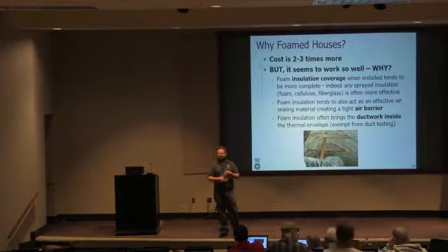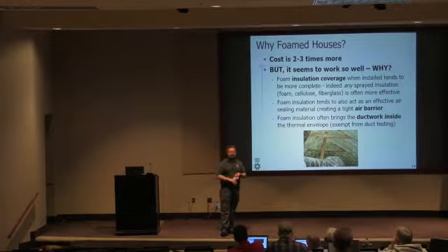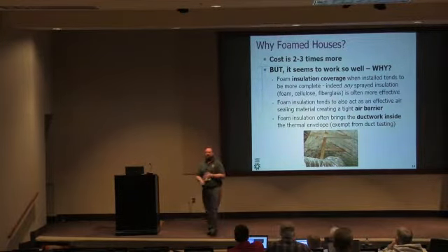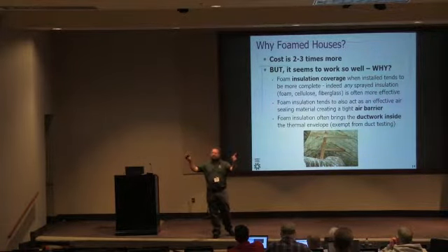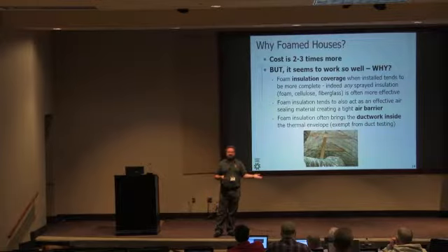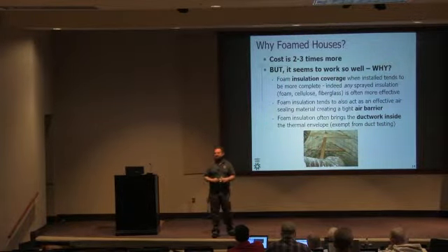Insulation is really crummy. Lighting, everybody's by and large still putting in incandescent light bulbs. They're not even getting to CFLs or LED for 50% of the homes. And duct systems installed in spray foam roof lines are not getting air sealed by mechanical contractors. And I get it. You don't have to do a test. That equals I don't have to air seal this duct system. It's cost. It's labor and material. So why do it if you're not going to have to prove it with a test?